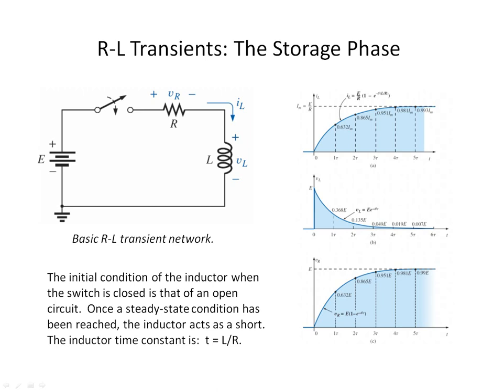As it's changing to reach that height, it's going to send current back opposing the I sub L. That's why the current on this plot is ramping up until it reaches its final value, where I is equal to E divided by R.